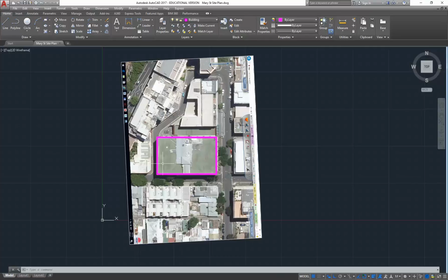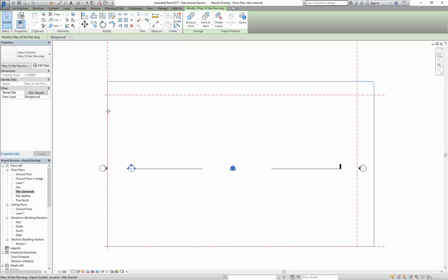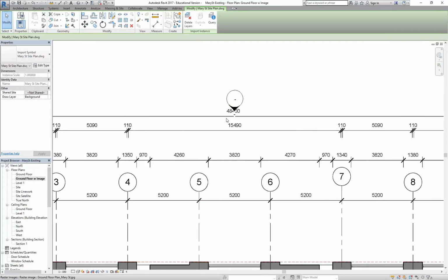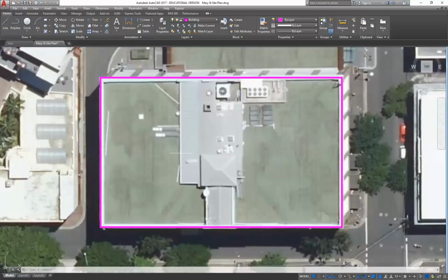So now I can go back into AutoCAD and use those same measurements. Again, you can see here it was 48400 and 28400 from memory. So maybe I'll just test your AutoCAD. What do you think would be an easy way to get those measurements for the rectangle here? Because you don't get the automatic dimensions coming up like you would with Revit, it's probably easier just to delete these two lines and this time use offset.